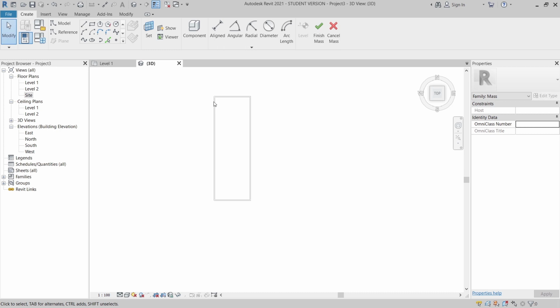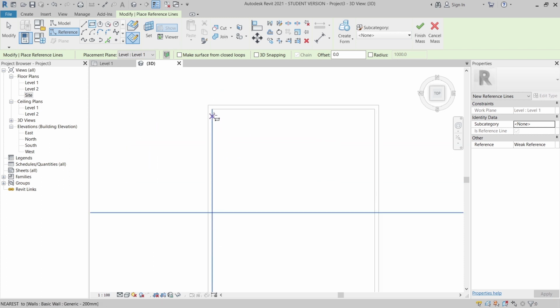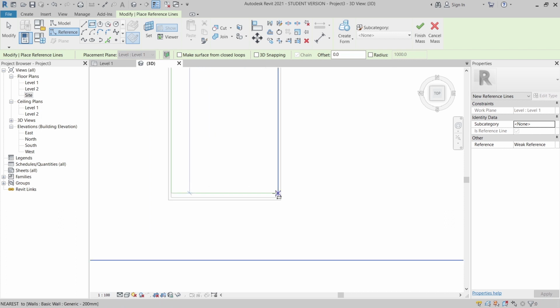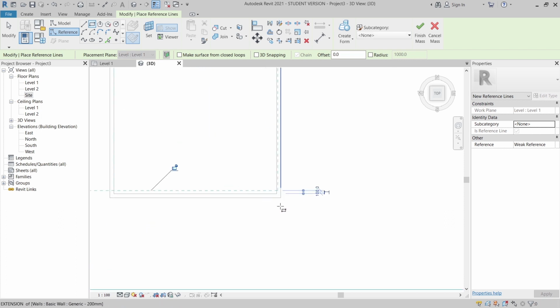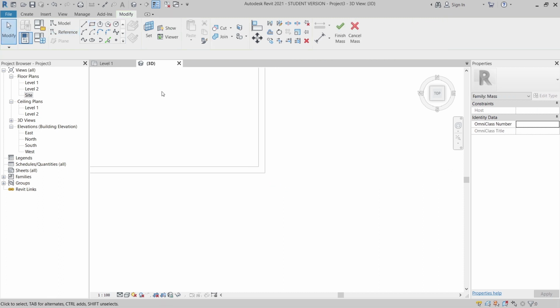Now it's time to create our ceiling shape. I can simply go to my reference plane, rectangle, draw on work plane, and take 3D snapping, and start the first point here, and the second point is there. Okay, I think I got something wrong. Hit escape first. I'm going to Control Z a few times first.